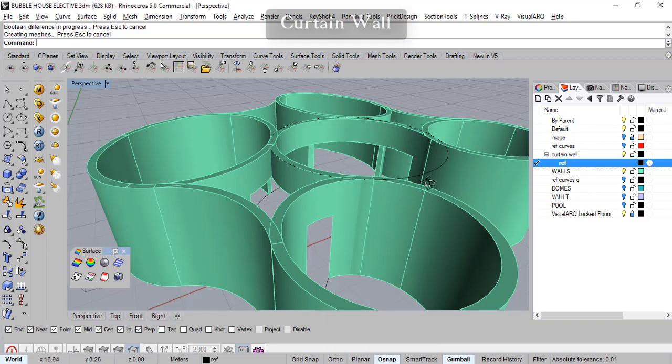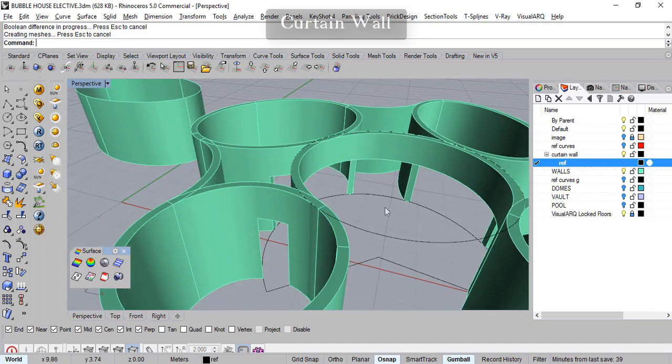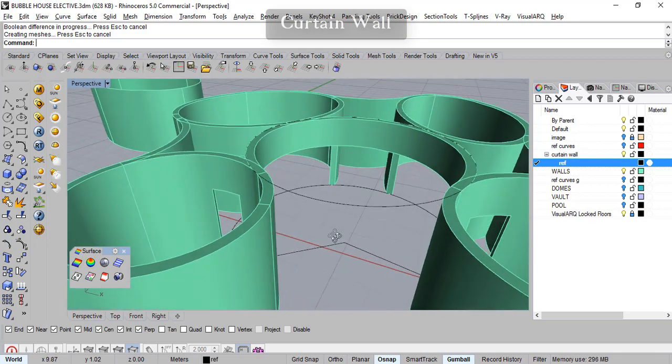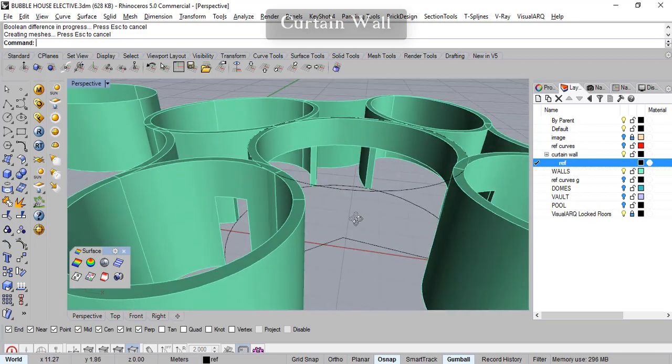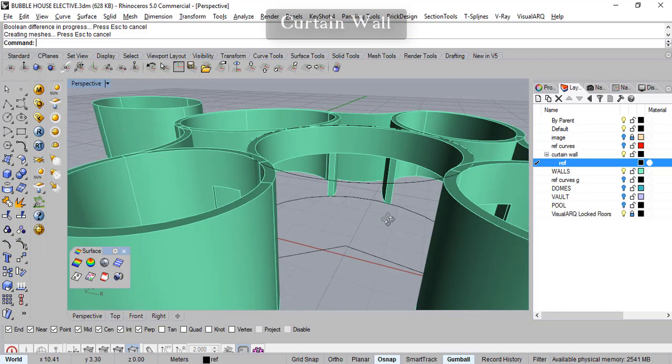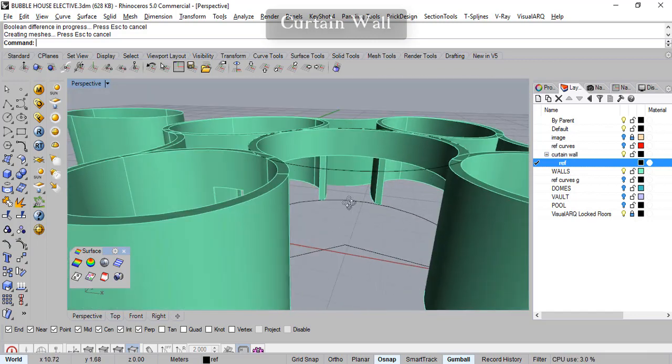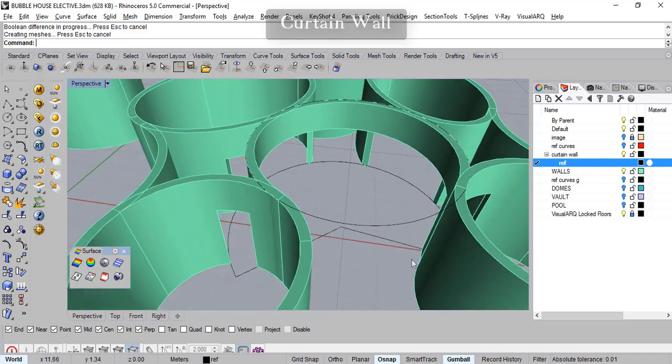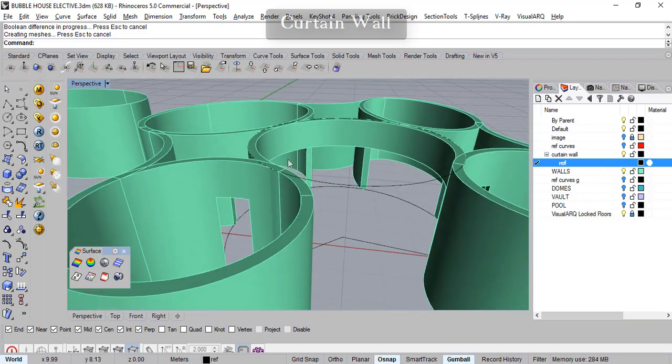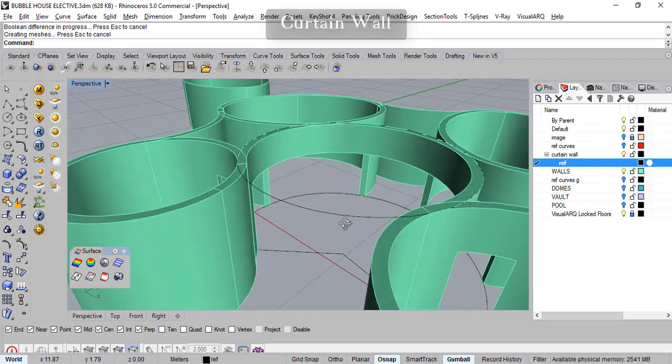So now what we need to do is essentially build the glass wall here, because we have the top edge. We'll draw up the plinth, and right exactly on top of the plinth we'll have the mullions put here in a border manner, and drop some sash member and just fill the whole thing with glass.